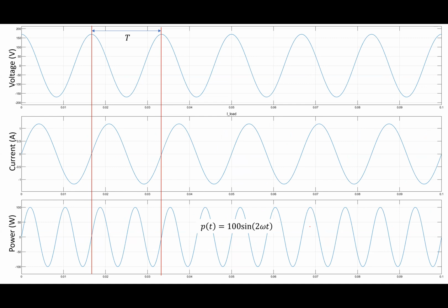What I see is that for the inductor, what's it mean when it's positive versus when it's negative? What's it mean for P of t to be positive? It's absorbing energy. What's it mean for it to be negative? It's sourcing that energy. That makes sense because an inductor is an energy storage device. For half the cycle, current is flowing into it to store energy.